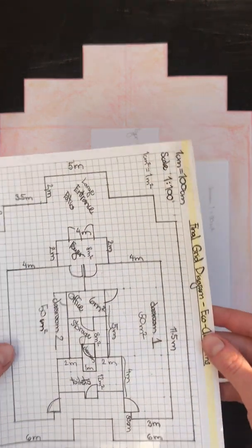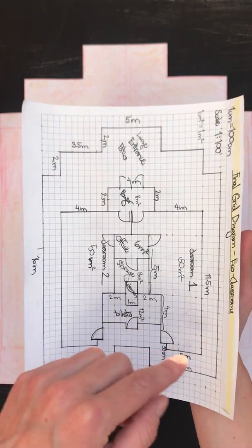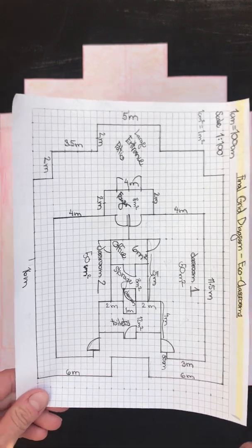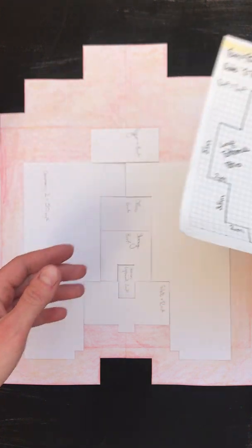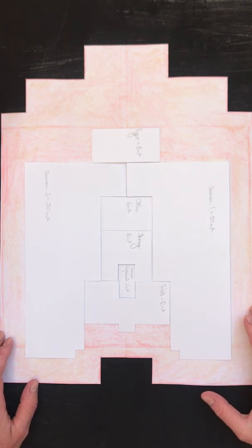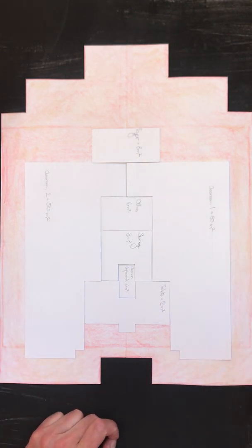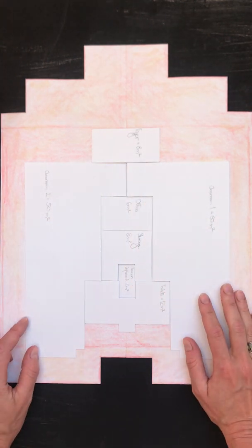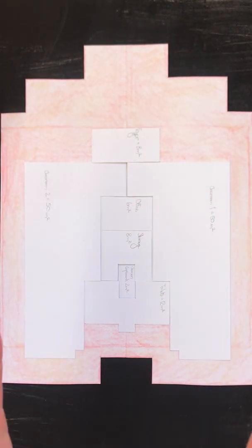Now, for now, I'm expecting you to choose your best grid diagram for your floor plan. You already have all your measurements. You have done that in the past lessons, and you now need to build on the knowledge and on the calculations which you have from previous work. And all I expect you to do is scale up, do your maths, get a card, get yourself a ground, which is perfectly to scale, 1 to 50, and start cutting out your rooms. Okay, for now, to build the foundation of our model, this is all I would like you to do.